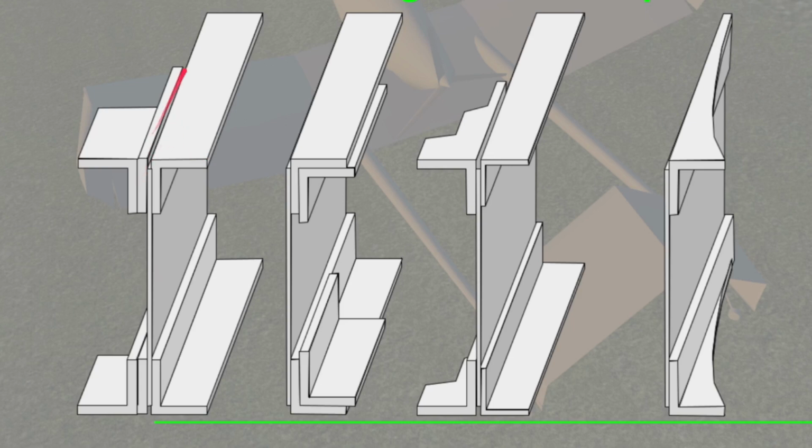Now, a spar is not going to have the same compression and tension forces out along its span. So you can actually have a beefier spar toward the fuselage and almost a non-existent spar out toward the tip. And so I'm showing here some various ways that you can have a beefier spar at this end. So the end closest to us here would be more like close to the fuselage. Out here would be closer to the tip.